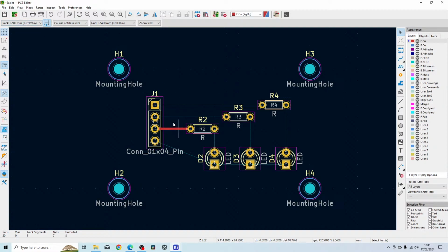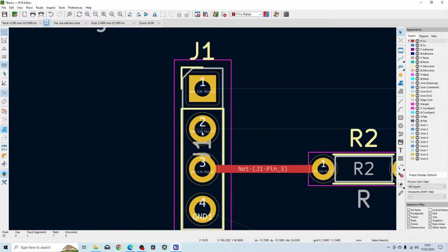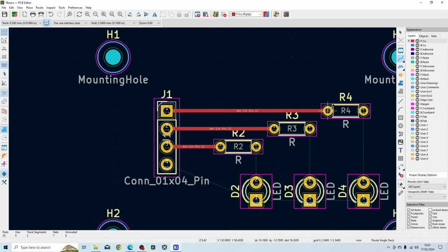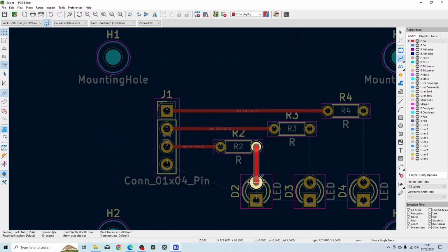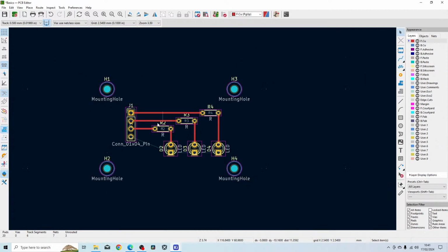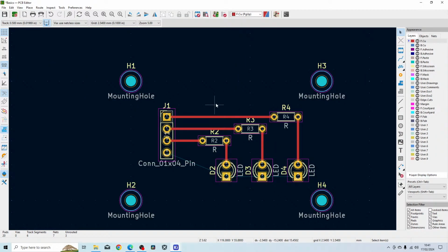And then if you want to make the connections, you can go to your through hole pad, in this case press the X button and then click, and click your left mouse button again. And you can see it's as simple as that. It's fairly easy to do. It's not complicated at all. But obviously this design is very simple. We can go on to doing a better design later on, or sorry, when I say better, I mean a more complicated design later on.